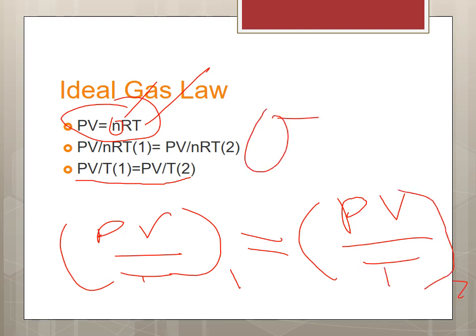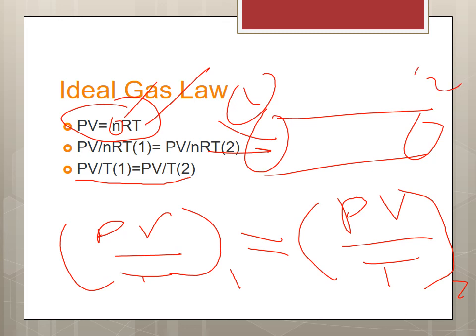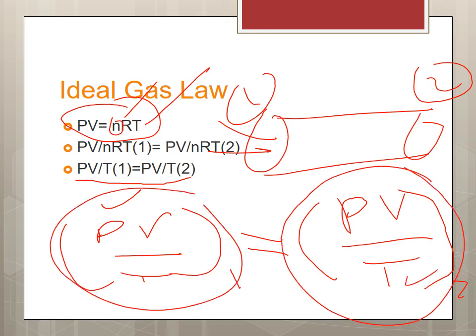So if we have a pipe and or if we're heating gas and gas is coming here at state 1, coming at 2, it will maintain this relationship, meaning if the pressure changes here, something has to go down here to maintain this relationship. So this is a way for us to control and know what is the amount of gas or air coming inside or outside the boiler. I want you to know that before you go into power plant, because it will be very important for you to know how to calculate the flow rate of gases and the flow rate of steam.